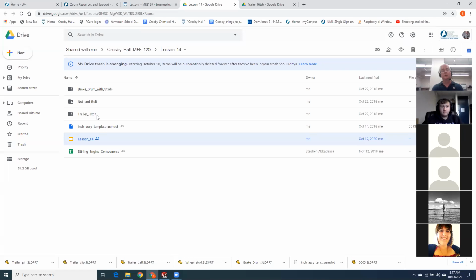Okay. Then, I had a quick one. Yeah, Sam. The graders for my drawing homework said she couldn't access the parts, like they weren't linked to the drawing or something. Do you know anything about how I would save it so they are linked? Okay, so it sounds like you fell into the classic trap. Did you save your parts and then rename them after the drawing was closed to clean things up or something like that?